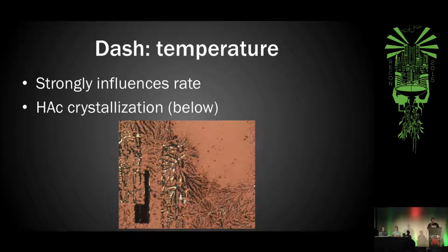So the way that I get around this is actually to use a heat gun, just like I was using for maybe decapping or some of the delayering work, and just run it at a slightly elevated controlled temperature so that regardless of whether I run this in summer or winter, I get a repeatable process running at about the same temperature. And below you can see an example of what this looks like when you do it at too cold of a temperature.